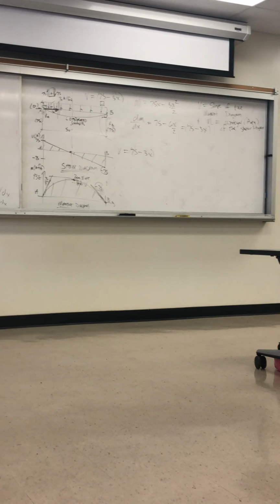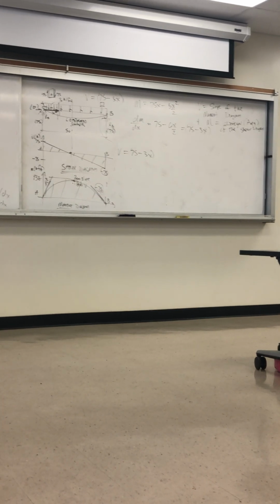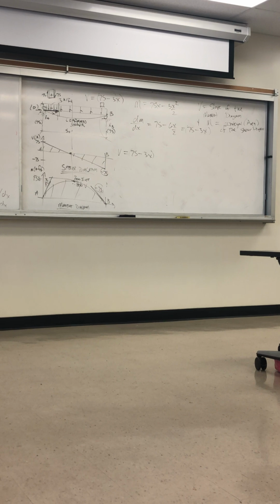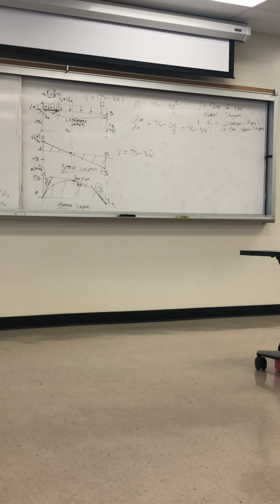A shear force is if you grab something, imagine a 2x4 beam, and you're trying to slide all the particles relative to each other. That's what shear is, across the section, okay? So it sets up a series of shear stresses across the whole cross-section. And you can look at any section, and the shear stresses multiplied by their areas have to exactly add up to the applied shear force across that cross-section. At every cross-section, everything's perfectly balanced.